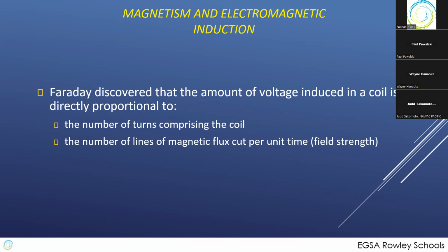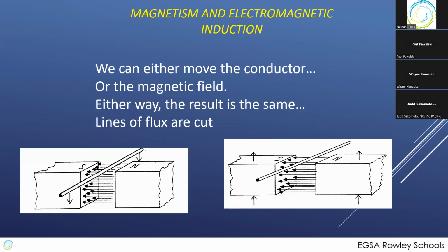power. And he found that the number of turns of the coil that's being used to pick it up matters, and the number of lines of magnetic flux, how fast the magnetic field is varying, matters. In other words, it was the stuff Oersted had discovered more than a century prior and didn't follow through on. And here's the thing: all that stuff you see on YouTube where they set up a magnet and get power from it continually, well, you already knew from your schooling that doesn't work. You need to have a relative motion between the conductor and the magnetic field, or you don't generate power.